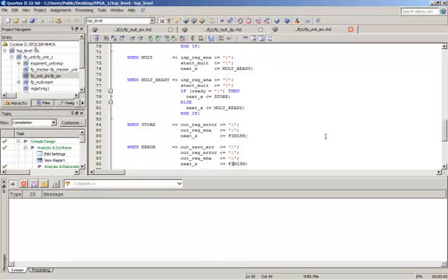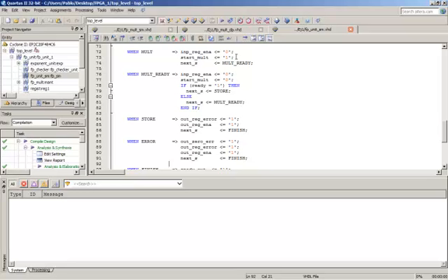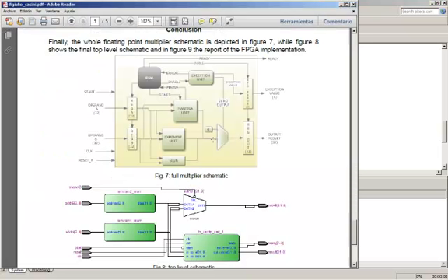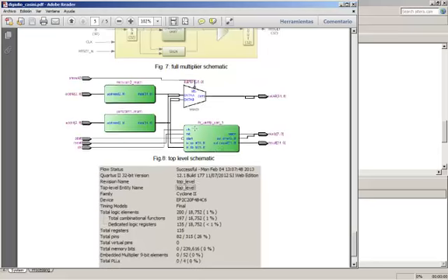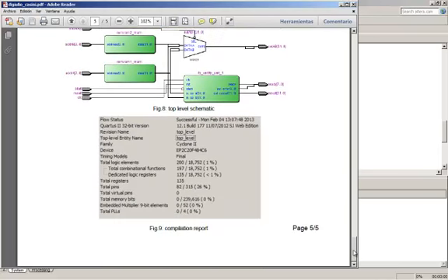In case the checker unit or exception unit returns an error, we must enable this register that latches the exception error value, so we can read this output and check what the exception was. Otherwise, we can get the value here at the output of the multiplication result. If we go to the top level of the solution, we see the floating point unit and also two ROM memories that are used to select the operands that we are going to multiply. We also have a multiplexer that can show on the board operand A or operand B. So this is the implementation of the multiplication using VHDL.